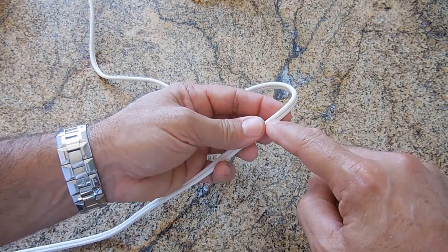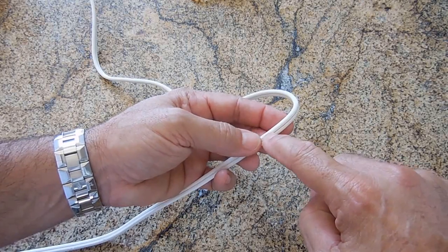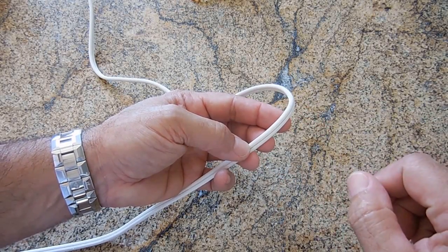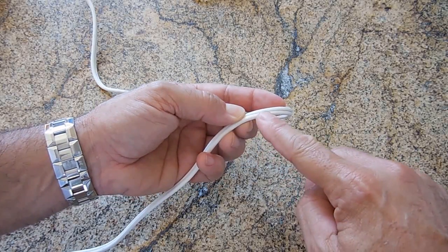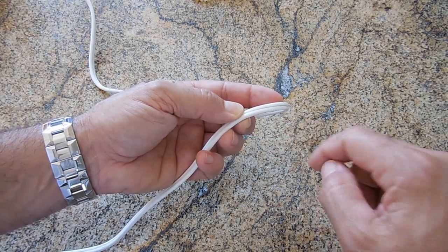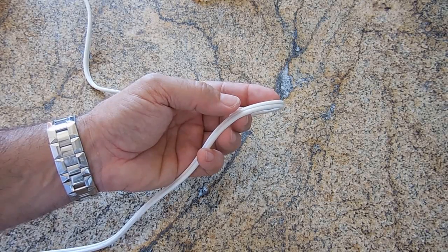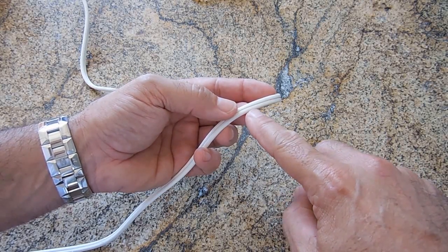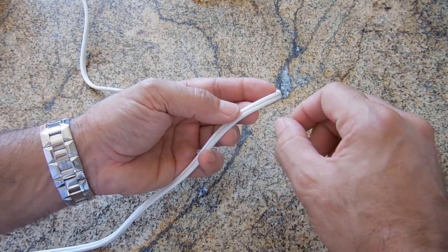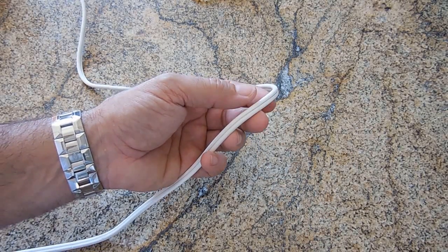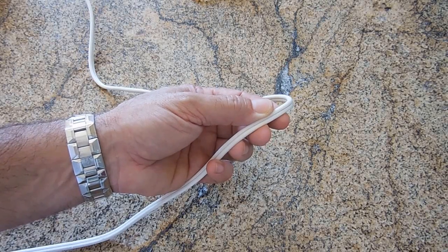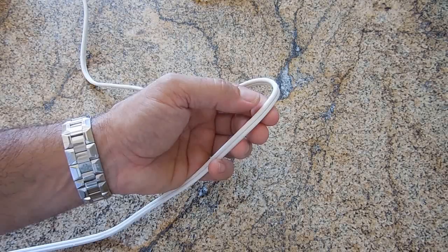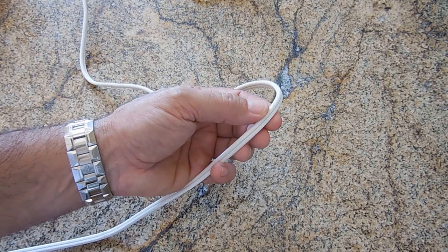If you look carefully on a polarized cord, you're going to see one side has ribs that run vertically. That is the neutral side of the wire, and the other side is smooth, and that is the hot AC line, in this case 120 volts. I'm going to be cutting a 1/4 inch section of the AC line, the hot side, leaving a space, and the switch will be installed right over that area. As the dial on the line switch is rotated, the circuit will open and close, turning the LED light on and off.